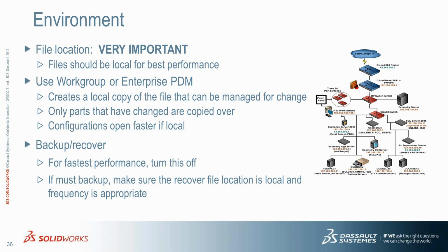So really the best answer for this, and I think everyone needs to get here, is to put one of the PDM systems in place. It doesn't matter which one, workgroup or enterprise PDM, but it's going to allow you to work locally on your machines. It's going to bring the data down locally. You're not communicating across the network for the whole time you're making the change, and when you're done, you put it back. And you really are going to eliminate a lot of possible headaches along the way.